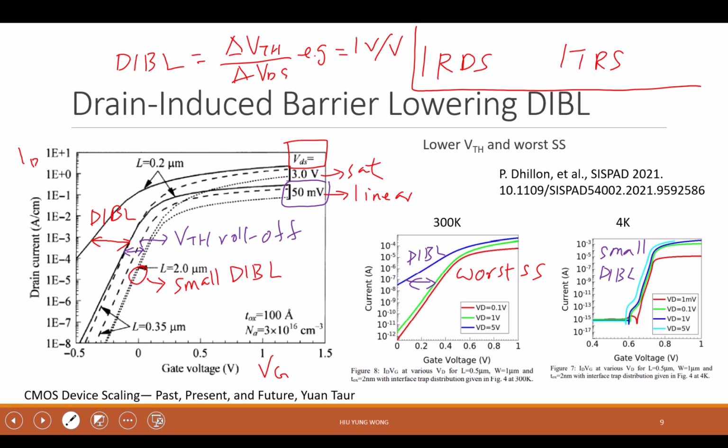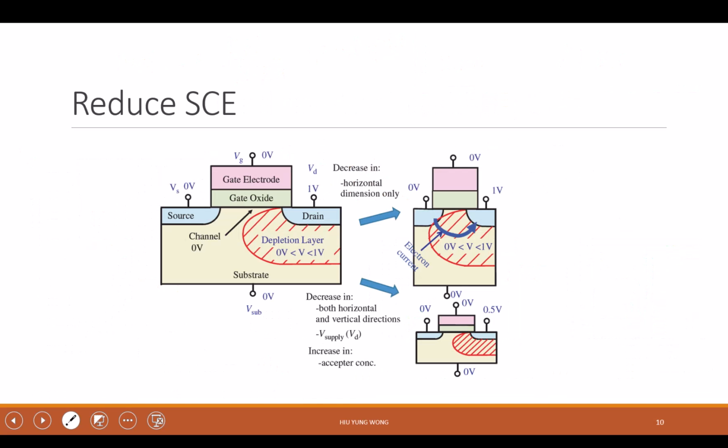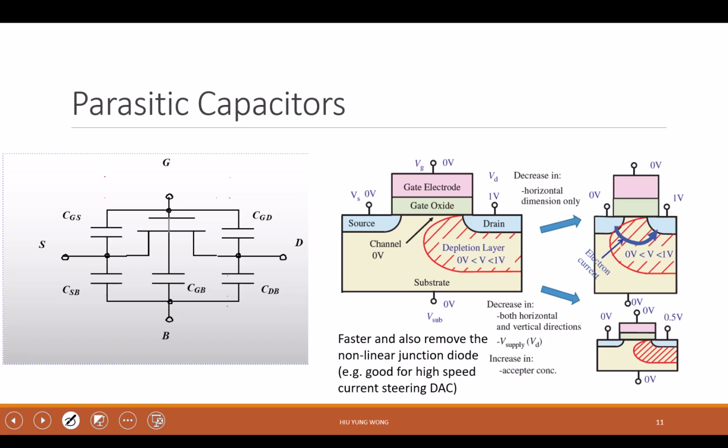So how can we improve this? Well, you need a better designed transistor. So in NMOS, they increase the doping, and because of increasing doping, they need to add the halo, which we did not discuss, right? If you refer to the advanced structure, which we don't have time for, but if you're interested, we can discuss in the future, or you can read it. But our goal here is this. The short channel effect is due to this ugly depletion layer. Can we stop it? If you add the oxide here, then you don't have this junction. Then you have much less depletion. And that's why we want to use SOI. SOI can reduce the short channel effect from this perspective, right? So we say that SOI can remove the parasitic